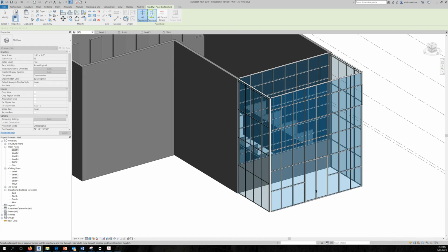Make sure, here it should actually draw a vertical one. That's what I want. There we go. So again, if you hold your mouse over the horizontal one, it should draw a vertical one. And there we go. And then again, to remove them, if they are continuous, you need to make sure that you use that add remove segment as I showed you for the grids.